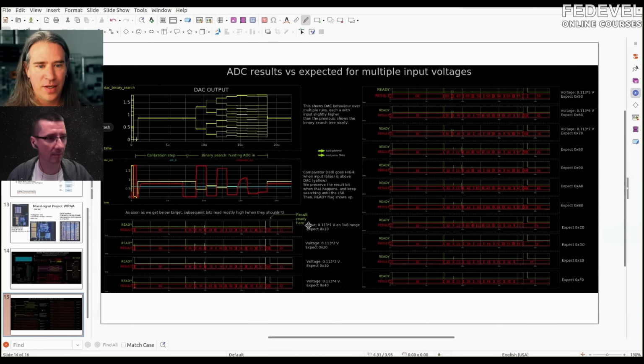And if you see the results here, they may be hard to see, but I did these tests and I knew what I expected. I expected a perfect ADC to give me these results in white. So hex 10, 20, 30, 40. And instead I got hex 11, 20, 31, 42. That's pretty good. Down at the end here in the high range, it messes up. It's like F. It just doesn't know what's going on. But this is the theoretical.